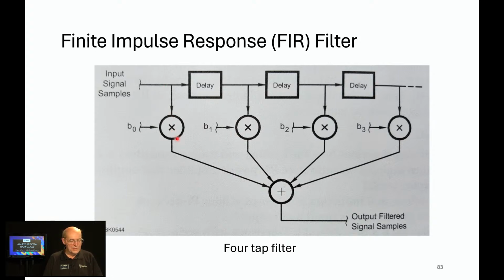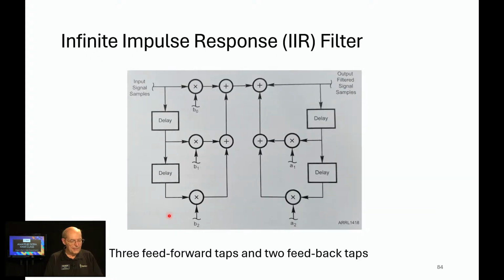So we've got the input signal, delay 1, delay 2, delay 3: a 4-tap filter, finite impulse response filter, very similar to an analog filter. And the levels can all be controlled here. That affects its shape, its selectivity, all of those parameters.